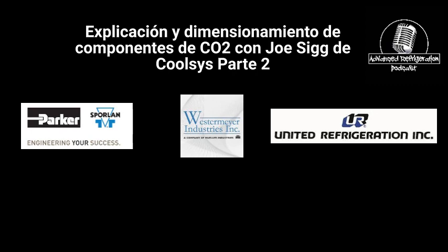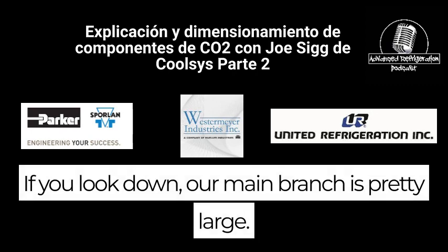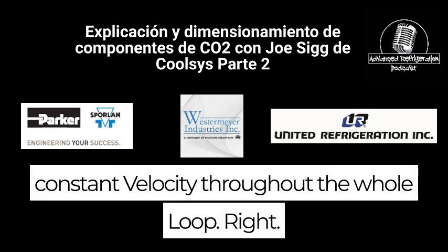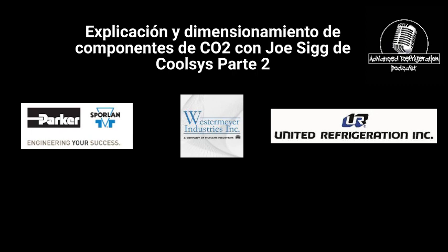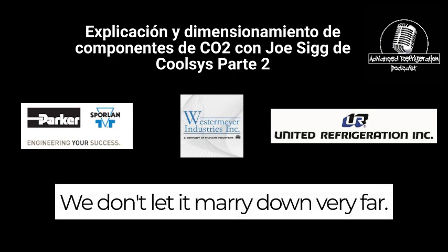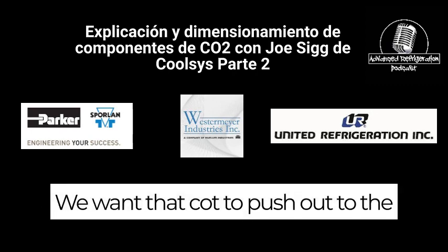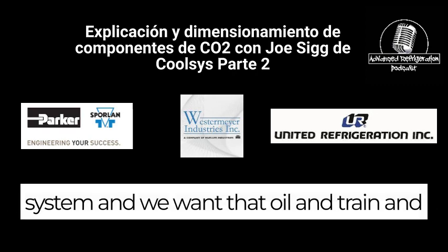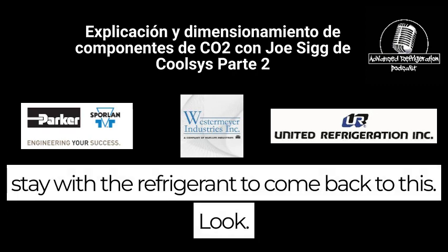But if you look down, our main branch is pretty large, but we maintain a very constant velocity throughout the whole loop. We don't let it vary down very far. We want that CO2 to push out to the system, and we want that oil to entrain and stay with the refrigerant to come back to the system.